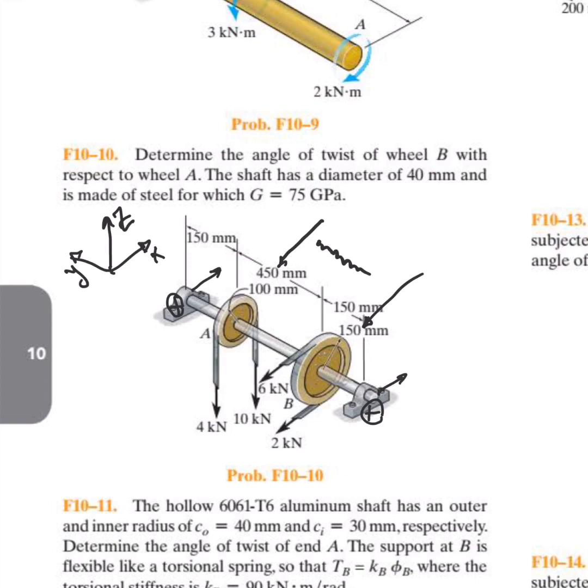Similarly, for the moments, because it's a three-dimensional object, we have 3 equations for summation of force in x, y, z equal to 0, and also 3 equations for summation of moments in 3 directions equal to 0. Let's just consider the summation of moment in the y direction. So I'm going to write it here: summation of moment in the y direction must be 0. If I sum them up, I'm going to get 4k.